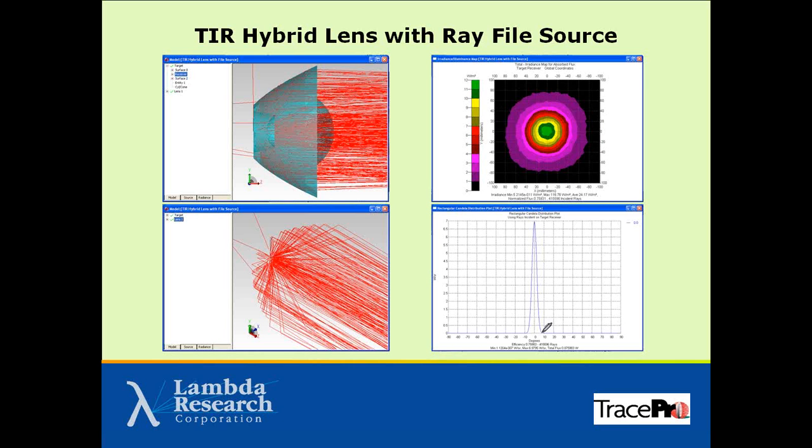Now we took the ray file for that LED. This is again that Osram Golden Dragon Plus. Downloaded the ray file from the Osram website. We can see here a little better resulting image in the irradiance map. Candela plots look similar. So again, we're getting better. We're refining the model here.